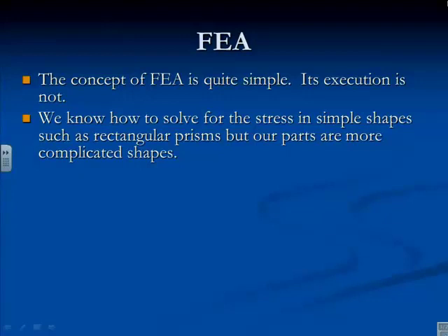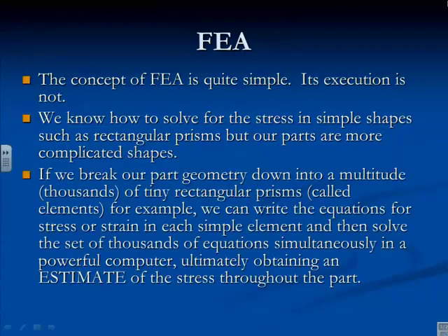And in the bad old days, before we had this FEA tool, what you had to do was simulate your crazy shaped part as a collection of these all put together so that you could calculate for the bits and pieces what the stresses were. In other words, I'd simulate something that was not quite a cylinder as a cylinder and that sort of thing. So there's a lot of error involved in that.